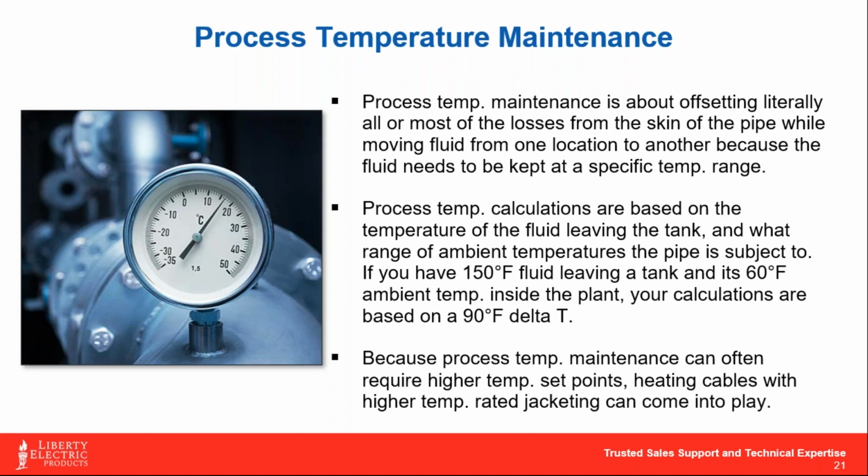Okay, so as long as there's flow going through that pipe, typically you're not adding heat to anything that's inside of it. But I can't say that if that was sitting stagnant in a pipe for an hour and your heat trace cable was running for that hour, that you wouldn't add heat to it.